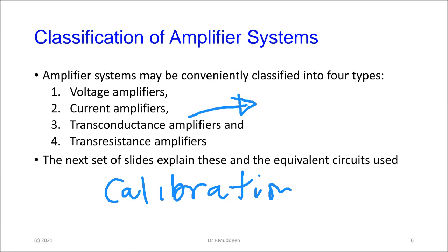So it's a very big job, and the cabling and everything is very heavy. But those are the kind of things used when you want to calibrate meters that read very high currents, like clamp meters and so on, although that's slightly different. You need to pump accurate high current from some source through the meter, and this is where transconductance amplifiers come in. If you ever Google transconductance amplifier or electrical calibrators, you will see them talk about that.